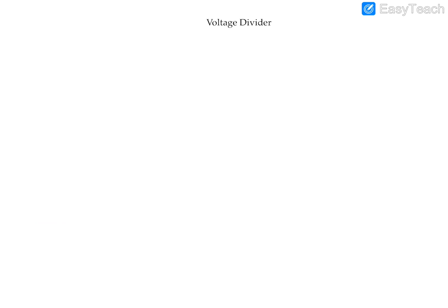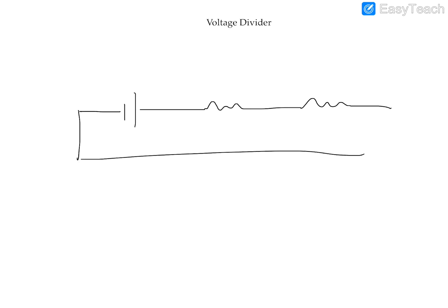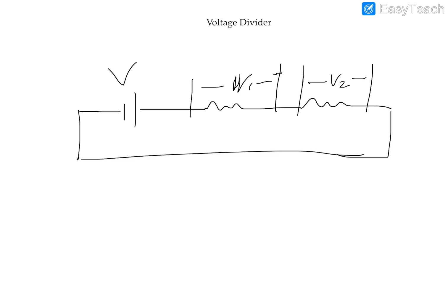It has many applications, and I urge you to explore them, but just remember, when you have current flowing in a series resistance circuit, the voltage will drop, and this voltage drop is exploited. In our case we had 12 volts, we dropped 3 volts across R1 and 9 volts across R2, and we took this 9 volts and fed it to our device.